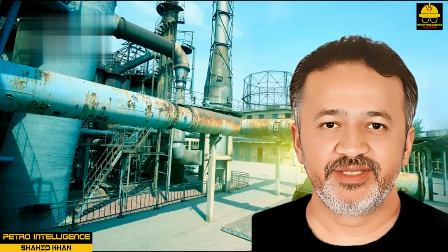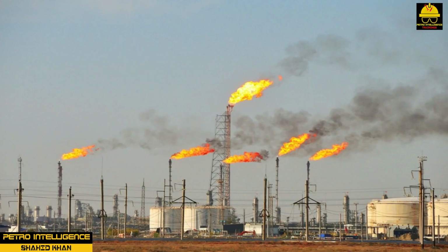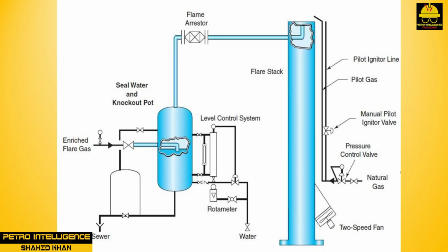Relief and flare systems. Flare systems are used to safely remove excess hydrocarbons from a variety of plant processes. Flare systems are composed of a complex network of pipes and headers connecting to a knockout drum and flare. Governmental laws and regulations require the flare to be located a safe distance from the operating units and populated areas. Flare systems are part of a plant's safety system.